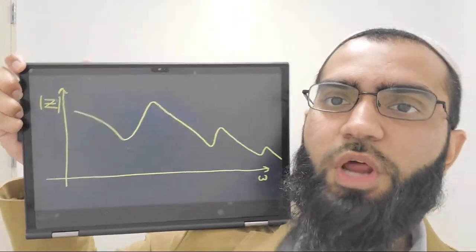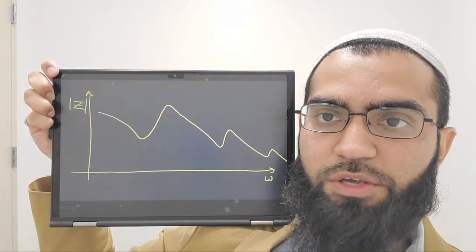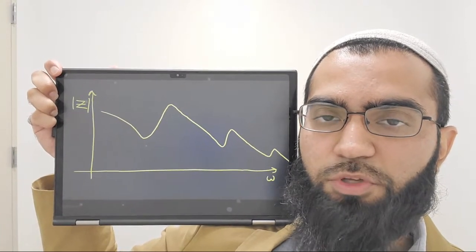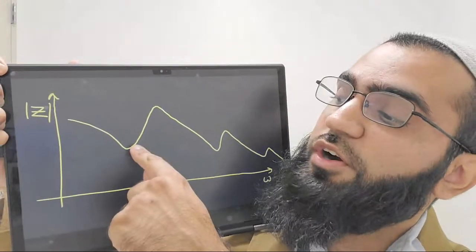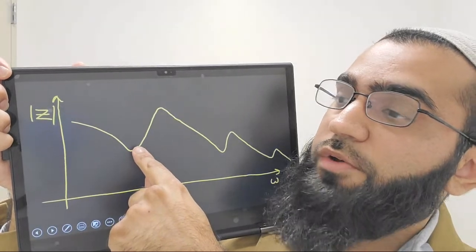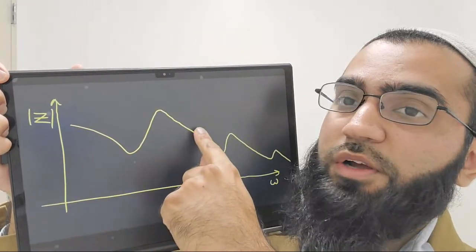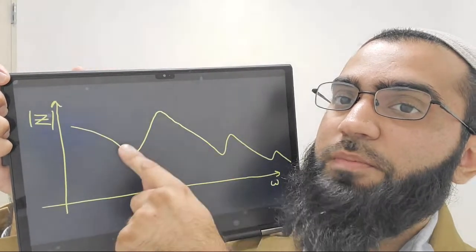Okay. So what happens if you have an impedance like this? We have multiple peaks, and you are driving using a square wave at different frequencies. Let's say you're targeting this mode here, and let's say your other harmonic lands right there. These are actually not too different in impedance.